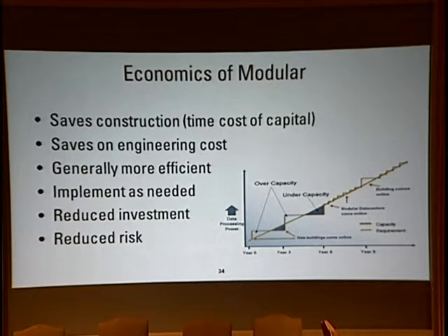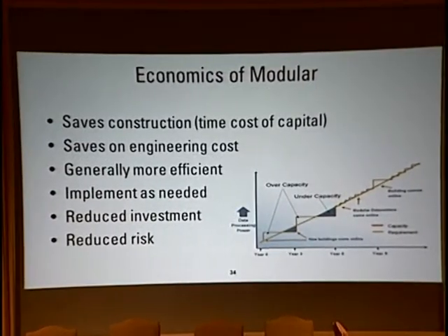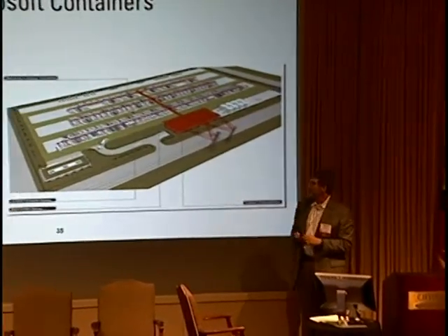You keep them highly loaded, you implement them in a series, or they're modulars inside of a shell that come in a megawatt at a time, even though you have a 10 or a 20 megawatt planned capacity eventually. The more you can keep your systems loaded close to their intended places, their high efficiency points on their curves, the better off you are. The better off you are spending capital at a timed rate, right? Time value of money. You keep your capital longer. You don't have to spend it on the equipment up front. There's a lot of advantages on the economics.